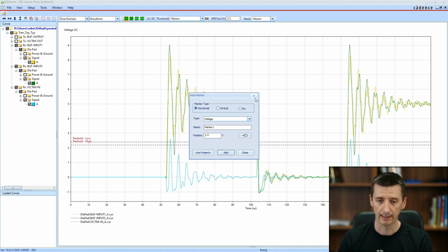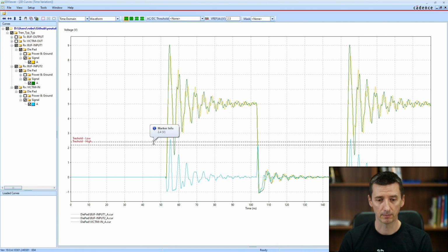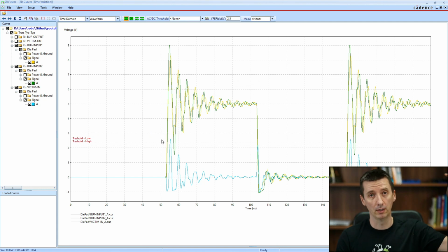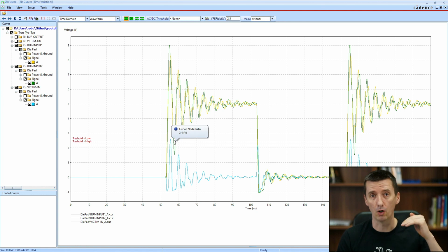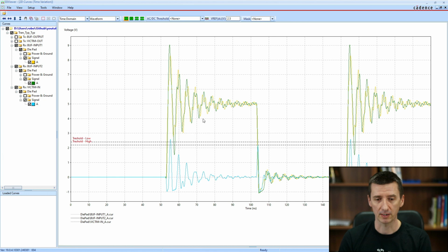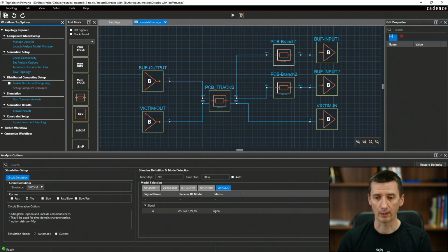And basically, any value going from high to low which is lower than this line, in this place, what we can see here, the buffer may register as an actual low value. So you can see this noise is so high that it can influence or damage the signal which you are transferring through our PCB.